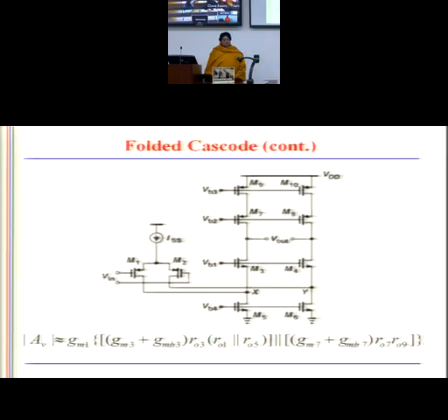Can you tell me the number of poles and zeros here? How many poles? If I say first of all the dominant location for dominant poles only. Otherwise I know what you will say, every node will give you a pole. So there would be so many poles. That would be fine. So tell me which nodes will give you dominating poles. That means their values will be small.